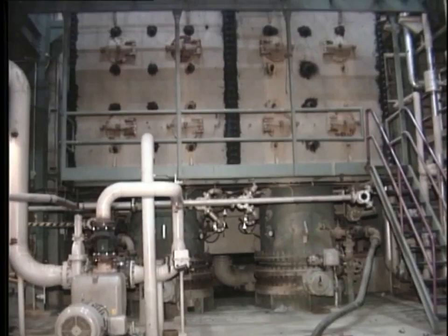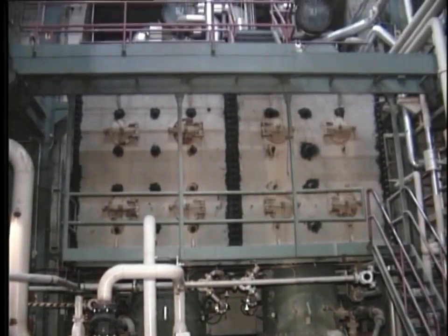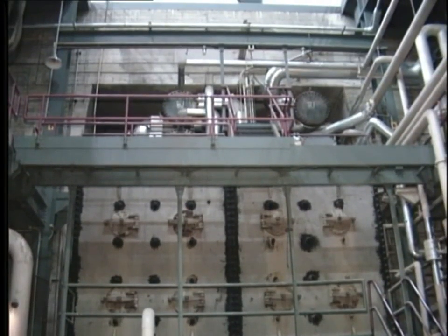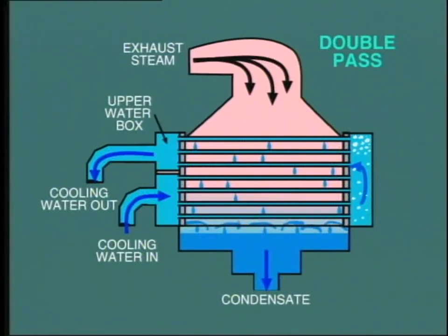Many condensers are fitted with a siphon connection on top of the water box. The objective of this vacuum connection is to ensure that the water boxes remain completely full of water so that all of the cooling tubes remain effective. But how could it be otherwise? Well, the circulating water will likely contain air bubbles which may be released at the top of the water box, forming a large air pocket. In time, as the air pocket increases, the level of the water at the top of the water box falls, and consequently there will be no water flow through some of the tubes.